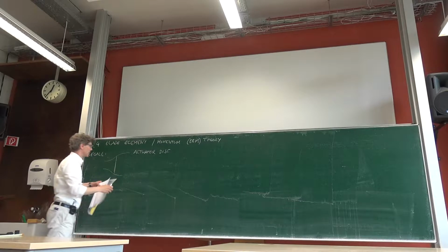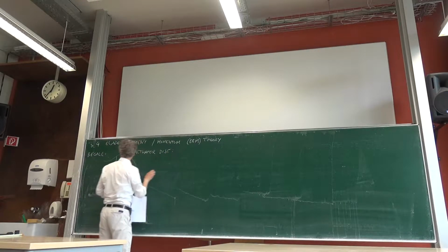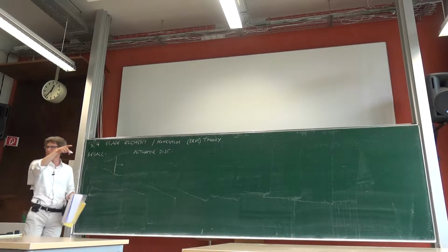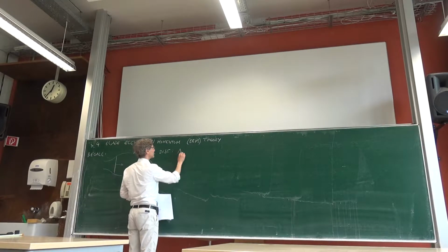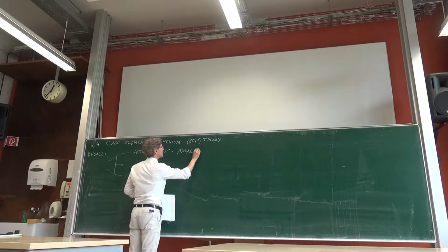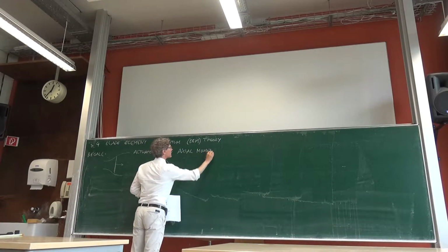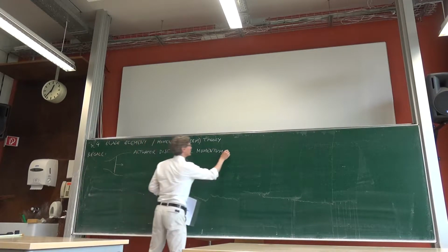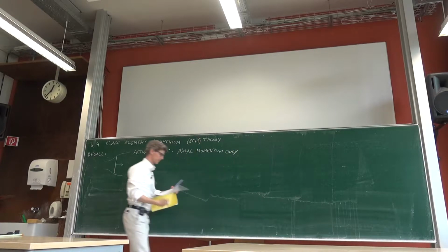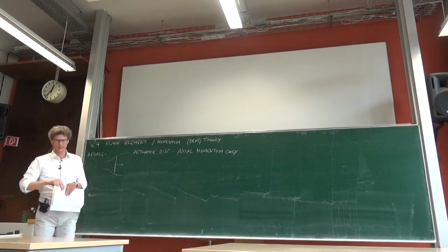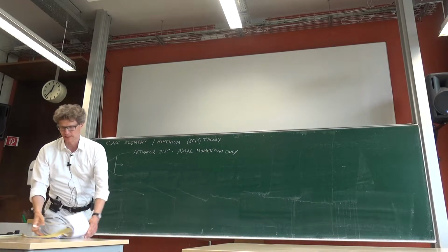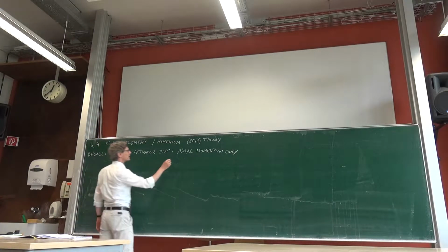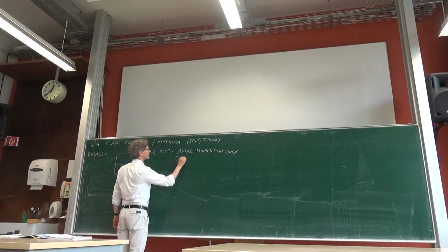And what was behind was everything was just taking place in this axial direction, in the direction of the axis. That's why we call it axial momentum. So everything happened only in this direction. Axial momentum only, and nothing else. And so the only assumption was that there is some disk and it exerts force, and with this we could already derive a few things, namely the Ct as a function of the induction.